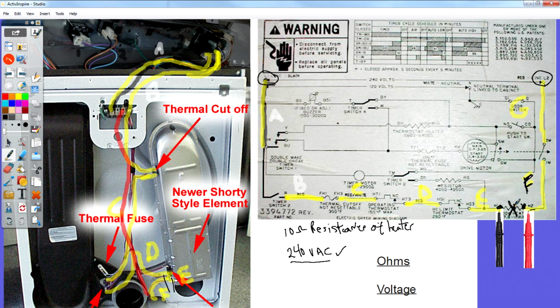If we went, I don't know where I drew that lamp, I erased it. But if we went to the lamp and the lamp didn't work, even if you didn't put a meter on it, what would be the first thing you do? Check to make sure it's plugged in. Okay? It's plugged in. Next thing you do is go get another bulb and put a bulb in here and see if it lights up. But the thing is in a machine, we have more than just one switch that turns it on and off. And these components are not as easy to get to. Plus, you don't have every part on your truck for every part inside this machine. So you can't just be putting a part on and say, no, that didn't fix it. No, that didn't fix it.